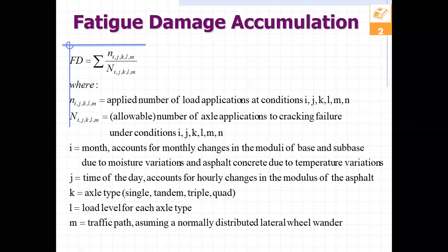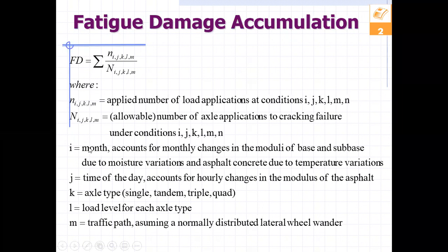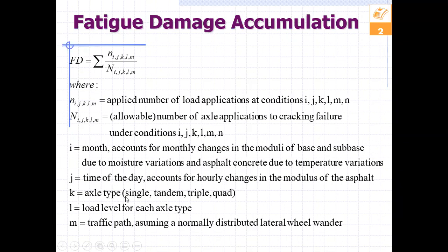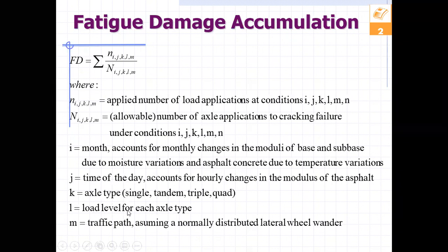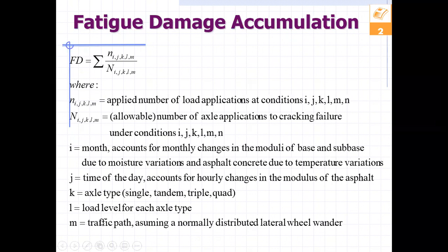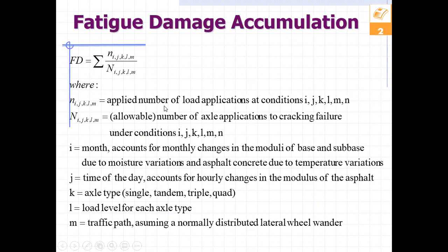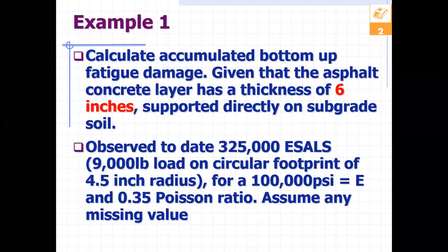One thing that I forgot to tell you is that the fatigue damage will be calculated for every month where the elastic modulus of the base and subbase might change. It will be calculated for every axle type, for every load level. It will be calculated for the wandering of the wheels on the traffic path. So I'm just going to simplify it a bit to be able to do it.